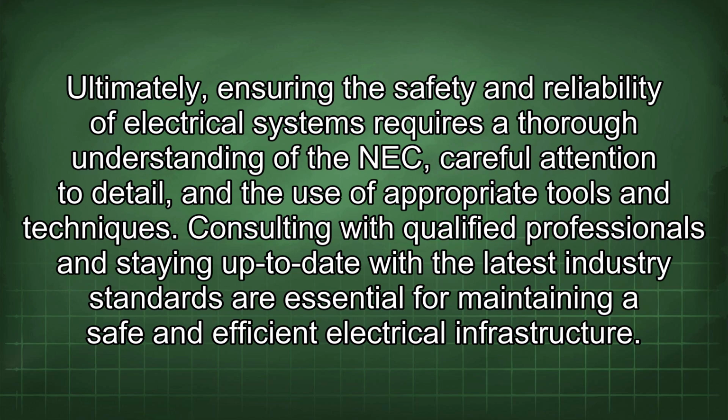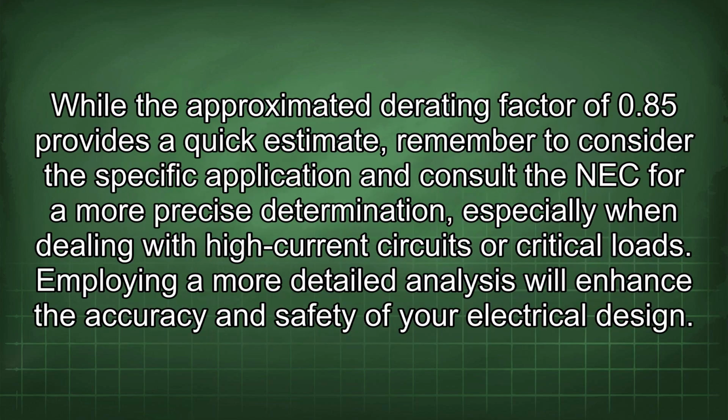Ultimately, ensuring the safety and reliability of electrical systems requires a thorough understanding of the NEC, careful attention to detail, and the use of appropriate tools and techniques. Consulting with qualified professionals and staying up to date with the latest industry standards are essential for maintaining a safe and efficient electrical infrastructure. While the approximated derating factor of 0.85 provides a quick estimate, remember to consider the specific application and consult the NEC for a more precise determination, especially when dealing with high current circuits or critical loads. Employing a more detailed analysis will enhance the accuracy and safety of your electrical design.